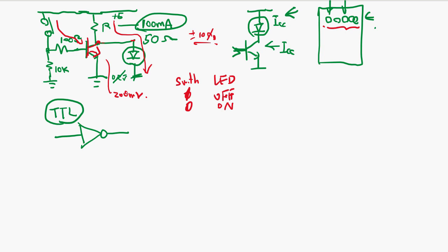Now an inverter doesn't have much function, okay, it just inverts. So how do we make, say, a NAND? And you know the entire CPU can be constructed by just NANDs, right? The NAND can be used for creating latches, flip-flops, and any other logic necessary. So a single logic element is enough to create an entire LSI chip, and we'll learn about that later.